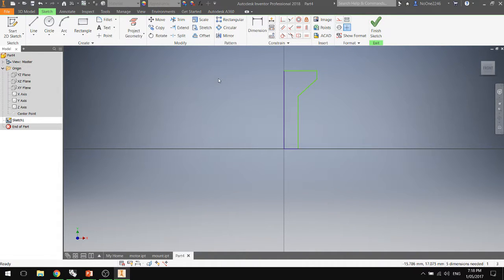It's no closed profile. You want to make sure that the profile is closed. If it's an open profile, then it'll try to revolve it, but it'll be a surface rather than a solid object. If you really wanted to, later on you could actually model a thread for the screw, but it's kind of beyond the scope of today. Don't have to model. You can just select 3 and then you can apply thread to a cylinder. Oh, well, there you go.